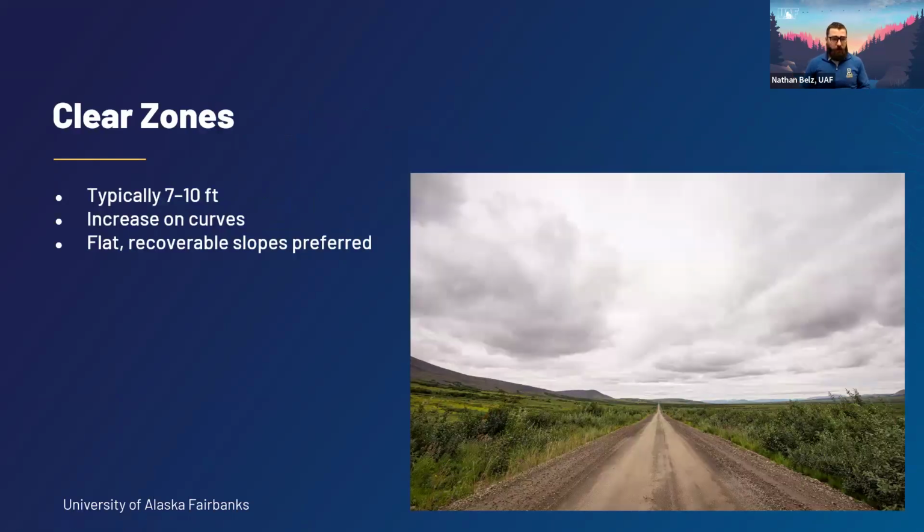So for clear zones, a clear zone being in effect a flat obstacle-free area along the roadside for driver recovery. If a driver were to start veering off the road, then perhaps they could steer and navigate back onto the road, or stop safely.